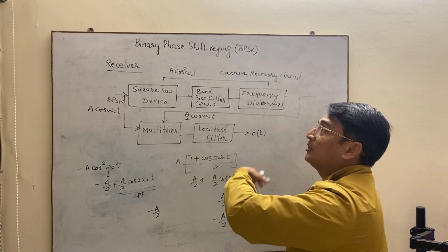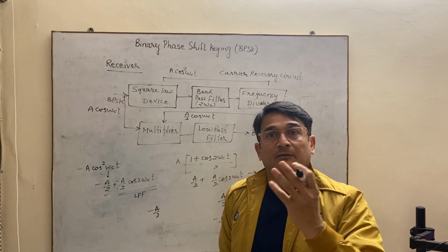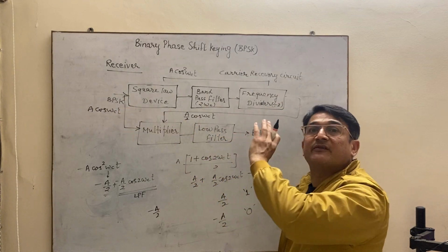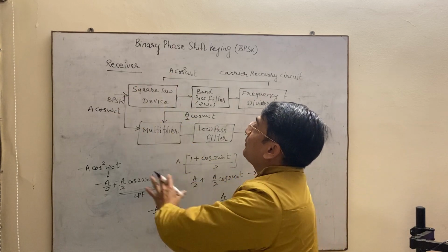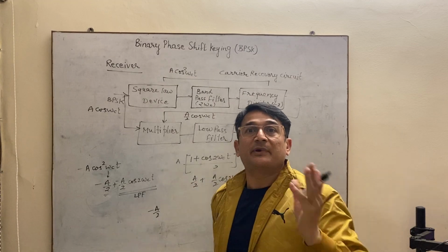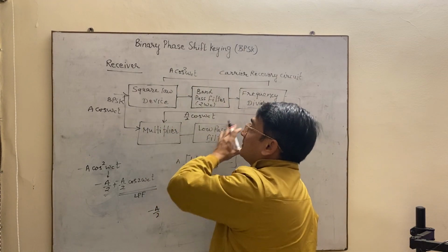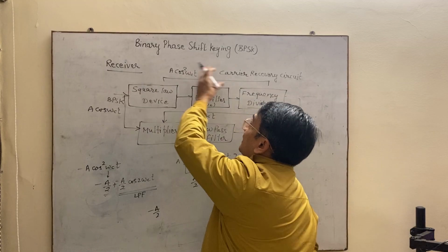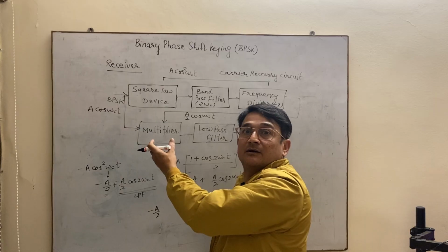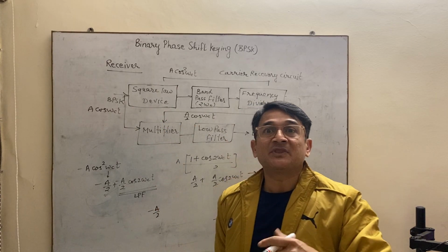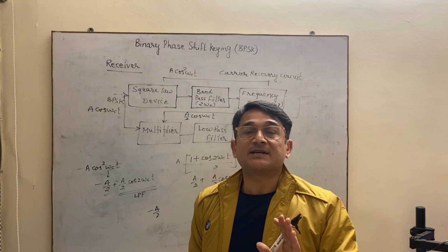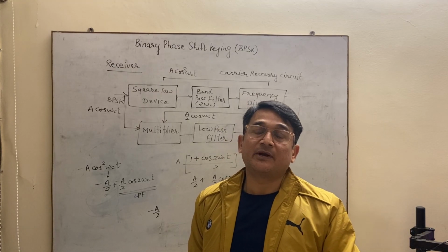This is how you receive bit 0 and bit 1, or in other words, you receive the whole bit sequence which you transmitted from the transmitter. This is how your BPSK receiver works. This is somewhat more complex circuitry as compared to ASK, but the carrier is recovered from the circuit itself, that is, the carrier is extracted within the circuit. So you can say this is better than ASK. BPSK gives better results as compared to the ASK signal.